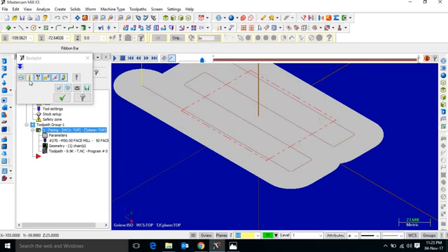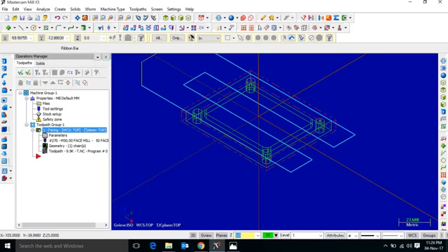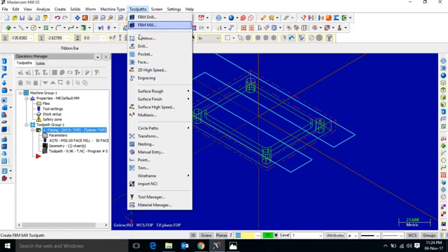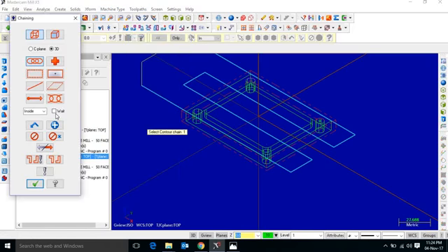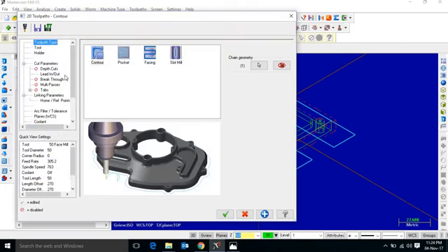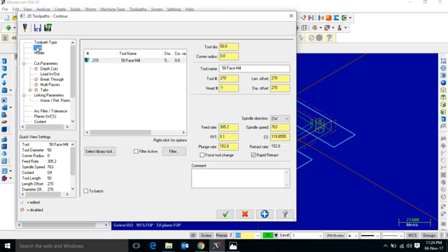There are different display options for the tool, so we can display the tool holder and all that. Select all, okay. Now we have to do the contouring operation to remove the 3 mm extra material from all the sides. Select the toolpath. In contour, select the chain. Okay. We have to do the 3 operations in this 2D toolpath contour: tool, depth of cut, and linking parameter.